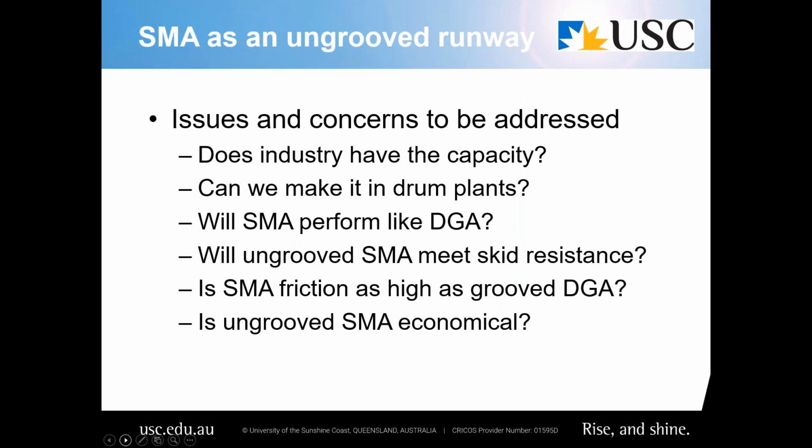Before stone mastic is embraced or accepted as a new normal within the airport industry, a number of questions needed to be answered, practical questions, such as, do the asphalt contractors have the ability to make this stuff? Can we make it in the drum style asphalt plants that we commonly use to resurface our runways?